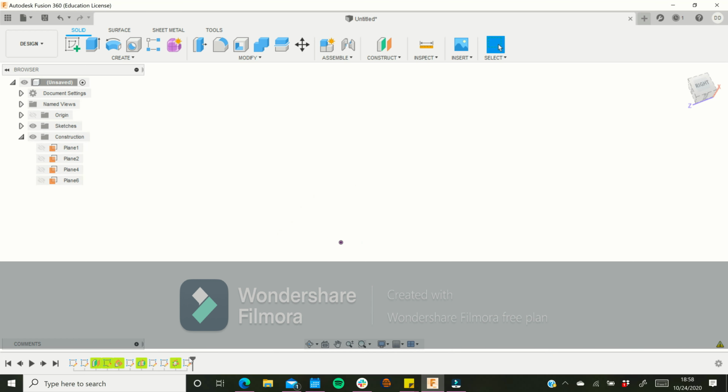And let's roll the time marker back. I'm gonna just delete all features after the history marker. A good thing with Fusion is it has this scroll bar for time on the bottom, and it allows you to just go back and forth in time for the things that you've been working on and doing in your design, in your drawing. So I'm going to select to delete everything after the history marker. So it's just going to give me a nice clean slate.